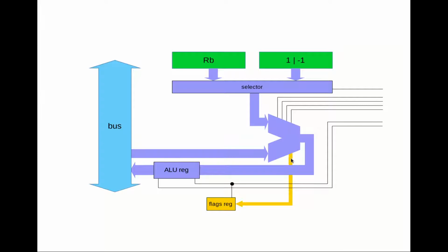But we can also use that carry flag in control logic. In our program, we can jump based on a carry. And we've seen a few examples of that in previous episodes, where our program will simply cycle through all possible addresses, and then when it's reached the last one, it'll halt. And we've typically done that using a jump on carry instruction. And so that carry flag will come out of the ALU for any kind of operation.